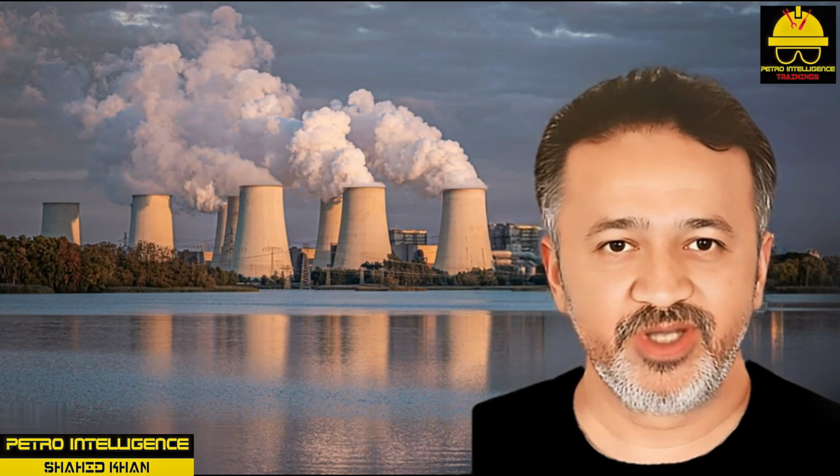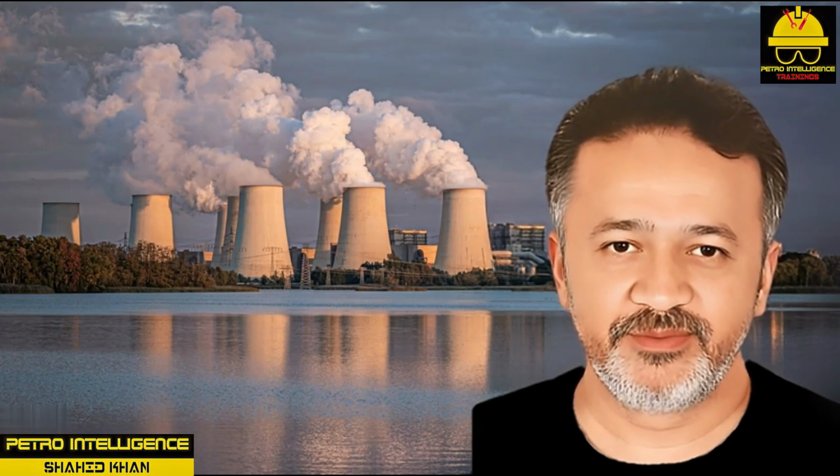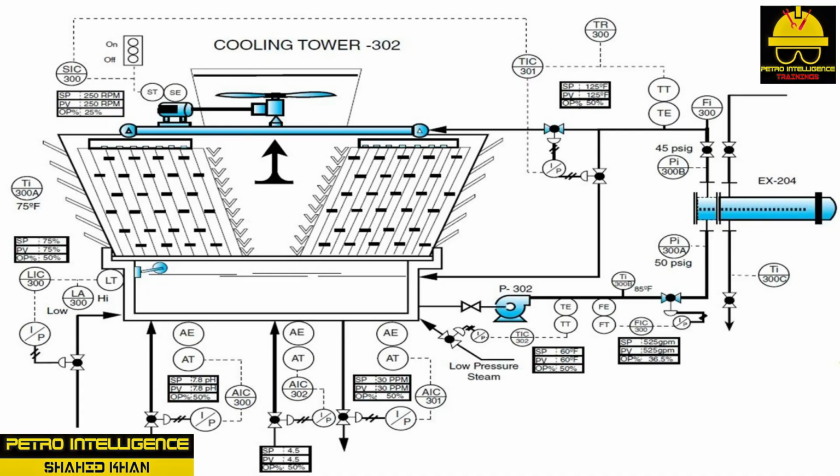Simple startup procedure for cooling tower system. 1. Notify your supervisor and all concerned about startup: downstream process technicians, I&E, engineering, maintenance, etc. 2. Ensure all safety hazards are secured: trash, locks, old permits, etc. 3. Check equipment and instrumentation: stroke control valves 0 to 100%, check lineups, etc.